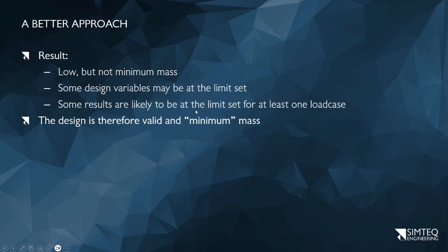And my results are all within key requirements. If you have to do a code calculation, one of the requirements may be that the stress for this load case may not exceed X. So these are the stresses and result limits that we specify. So valid, in other words, means none of my limits are exceeded. I'm entirely within the allowed range.